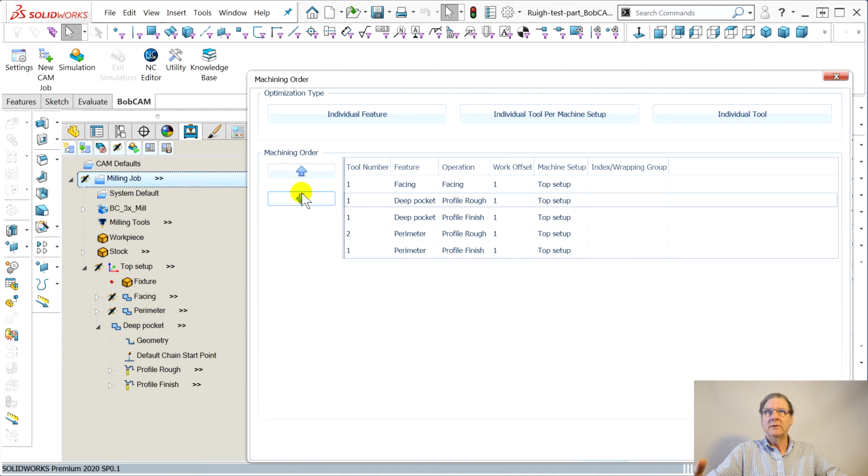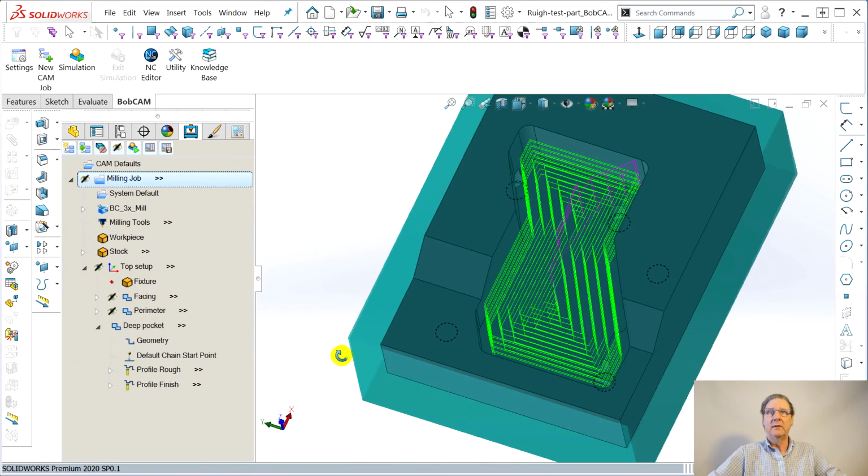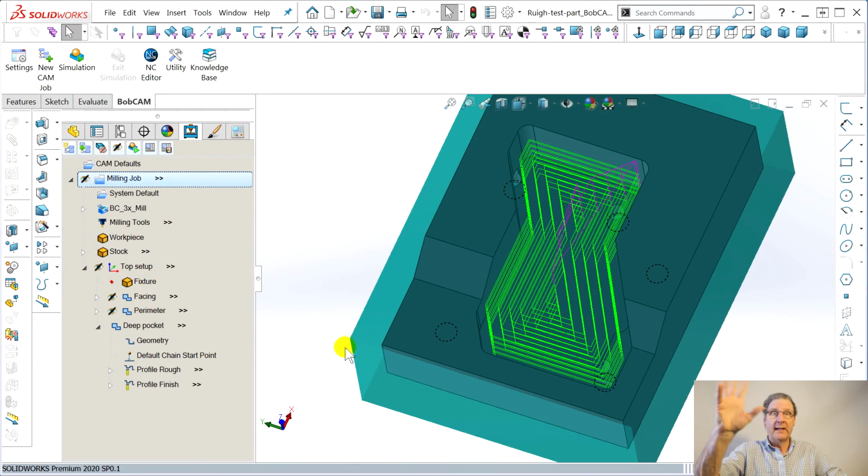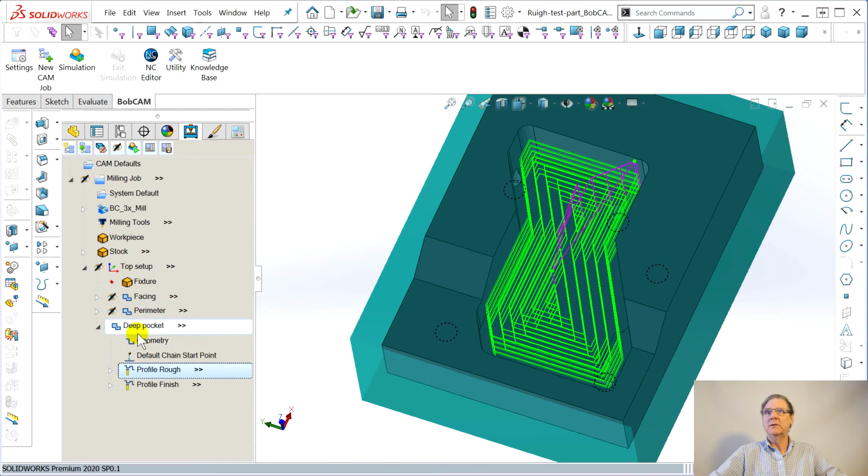Now, do this deep pocket afterwards. And then this deep pocket I also want to do afterwards. I want to do the rough and finish because it's the same end mill, right? If I was changing from a hog mill to a plain one, you could understand all this. So do the perimeter, rough, finish. Good when you saw this, so you know it's there. Although I suspect that 1/4 flute tool I've got floating around here somewhere is doing that to us.